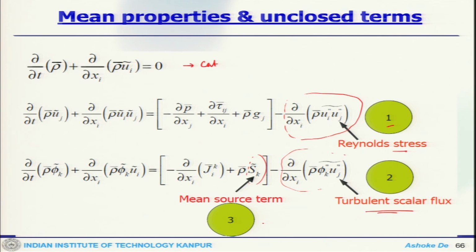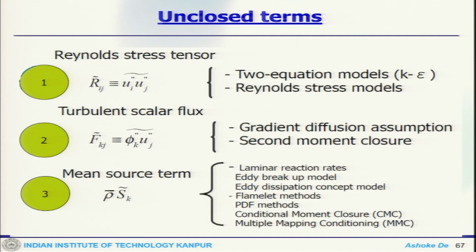If you look at the complete governing equation, these three terms are not in closed form. So, we need some sort of closure approximation for these terms, and this is one of the challenges one encounters. Now, when you try to close this Reynolds stress term, this is where you need to invoke your turbulence model. Your turbulence model will allow you to do this, so either you can use different kinds of RANS model or LES model or whatever it is. So, it is a variant of turbulence